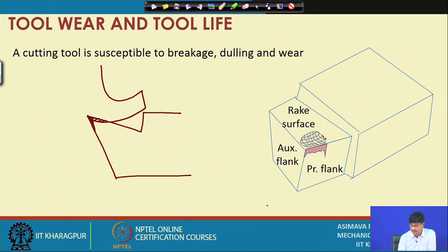Here also a sort of edge will form, edges like these, and here I have tried to show a crater-like feature on the surface. This geometric feature is going down from the rake surface. Okay. It is a worn away crater.